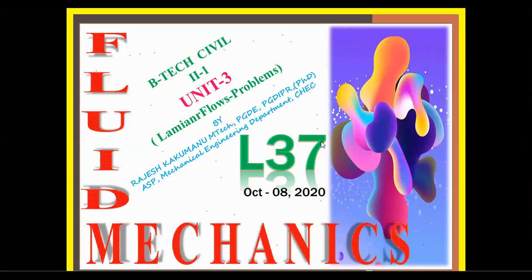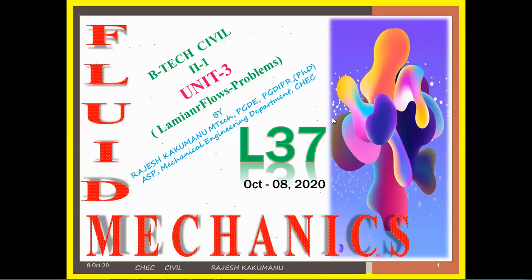In the last class, we discussed the turbulent flow problems, the smooth and rough boundaries in a pipe, related to the average velocity problems. Today in this class, we'll discuss the laminar flow problems. In the initial classes, we derived the Hagen-Poiseuille formulae, and based upon those formulas, we are now discussing the problems related to them. There is a laminar flow. Laminar flow comes under Hagen-Poiseuille's formula, whereas the Darcy-Weisbach equation comes under the turbulent flow formula, right?